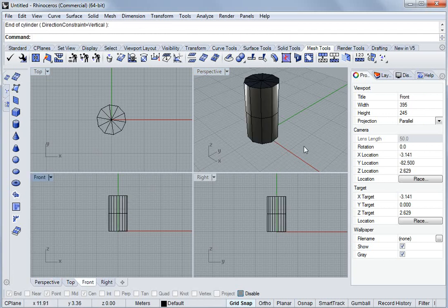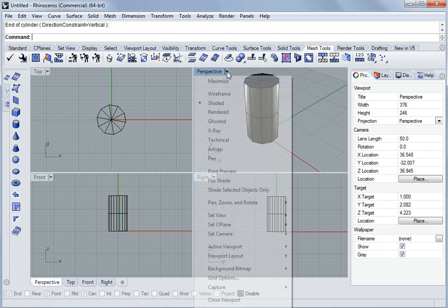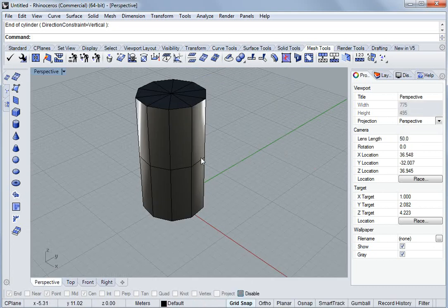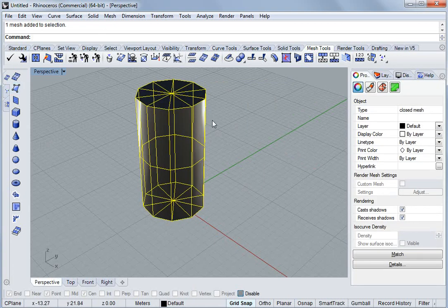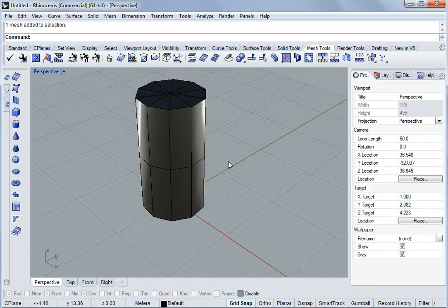Now, it is very important to be working with a closed mesh. FlexPDE will be filling the volume of this mesh, so if it's not closed, then that will cause errors. The first thing to do is to name this mesh. This name will be used in the PDE script to assign material properties to the volume.